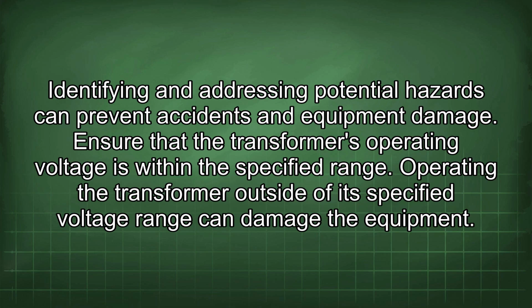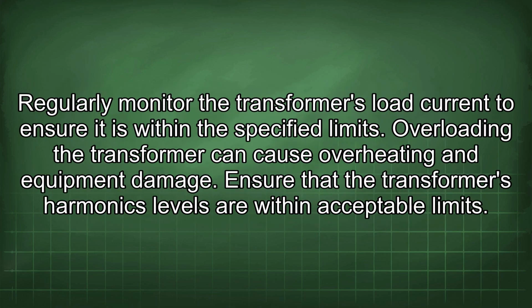Ensure that the transformer's operating voltage is within the specified range. Operating the transformer outside of its specified voltage range can damage the equipment. Regularly monitor the transformer's load current to ensure it is within the specified limits. Overloading the transformer can cause overheating and equipment damage.